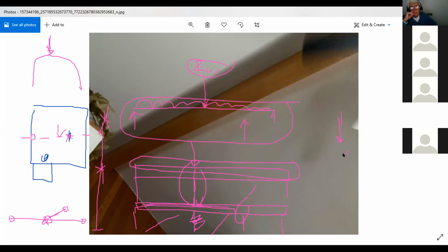It's a cathedral. Yeah. And this beam here is right in about the middle of that. In other words, if I look at the pitch of your house, this beam is sitting right here like this. Is that it? Yeah. Then this is not aesthetic, this is structural. If you're telling me that you have rafters, that's a structural beam.